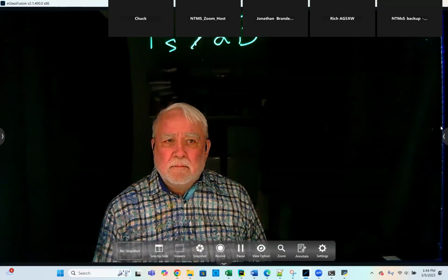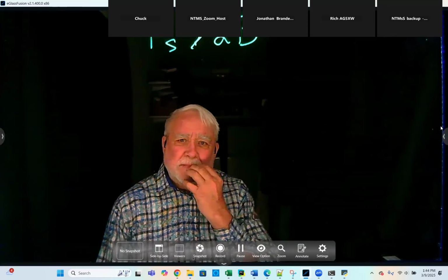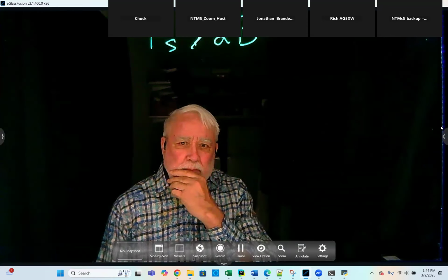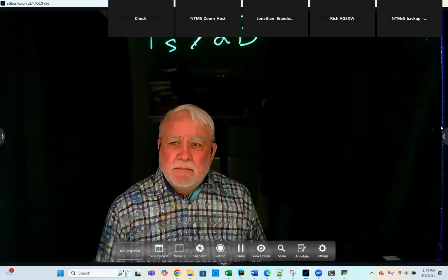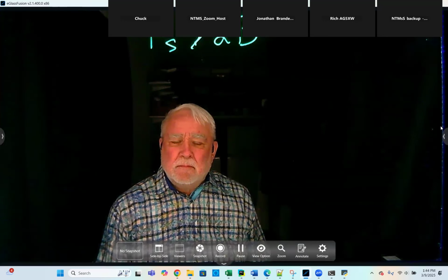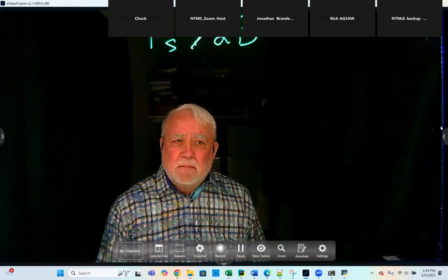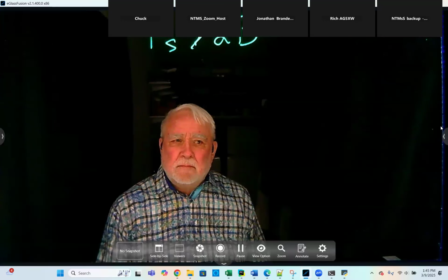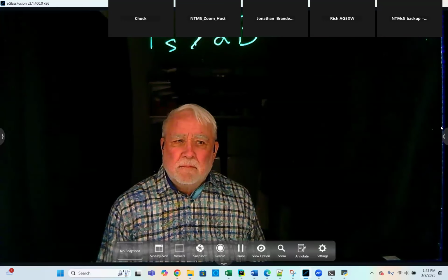Looking at sampling in the first Nyquist zone, which is what Jim's showing, I think the Pluto samples in some of the higher Nyquist zones, and so does the RTL dongle, which is a way to make do with a slower A to D converter.